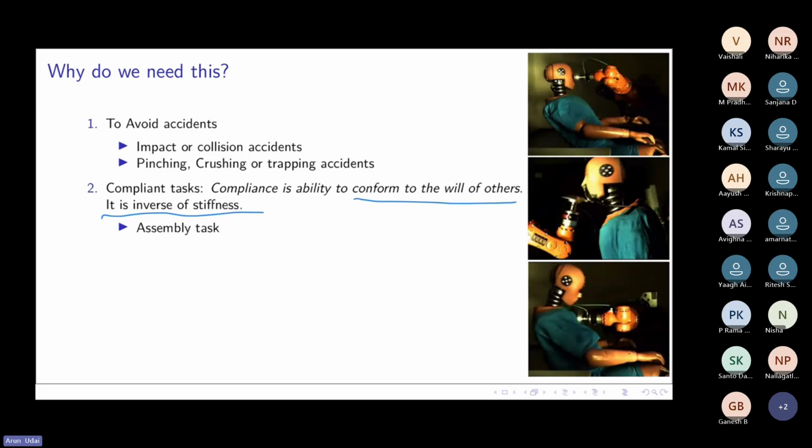You just go near the hole, the approximate location. You just move your hand, and while moving, you monitor your forces. You monitor the micro forces, and then you adjust your motion accordingly, or it gets adjusted on its own due to the constraint in motion. Finally you keep applying a vertical pressure and it gets inserted. So that is how it is done, right?